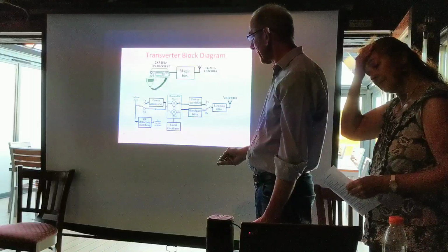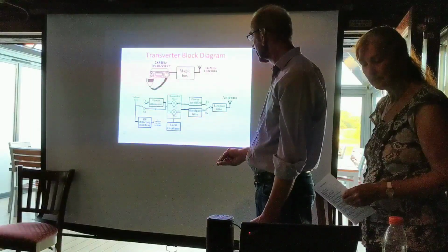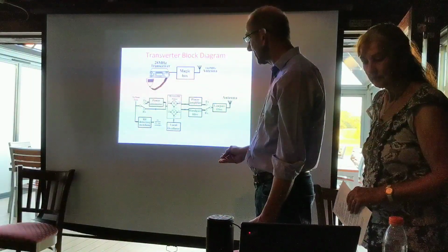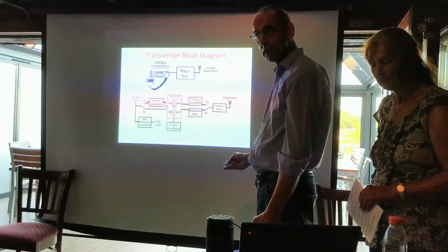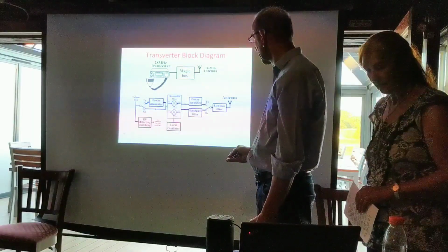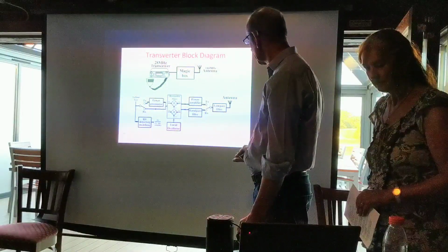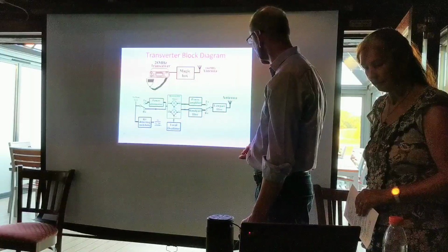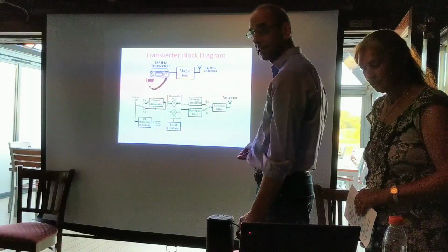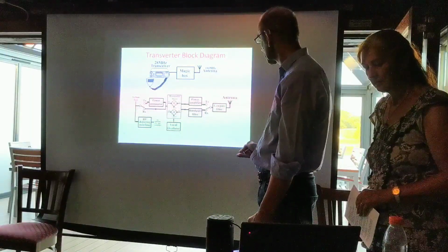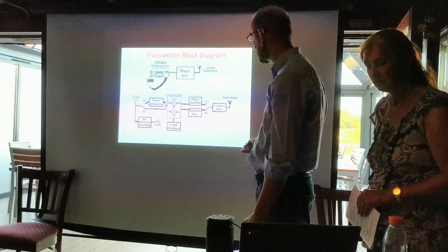We then go through the power attenuator, as we mentioned, to reduce the level, into a mixer, but the mixer now has to be able to go both directions, be switched round either way. We need a power amplifier, and we need a switch to route the signal through the low pass filter, which is there to get rid of harmonics of that transmitted signal, and onto the antenna.